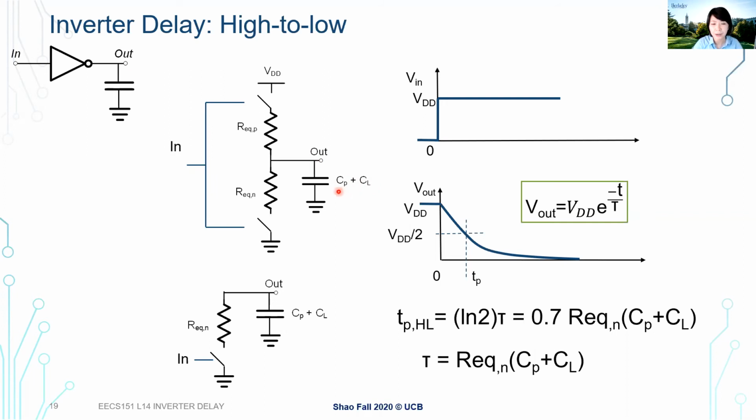At the same time, whenever we think about transistors, there's also parasitic capacitance associated with the transistor itself. So the capacitance affecting the output is a combination of the load capacitance, things happening after my output, and the parasitic capacitance, things happening in my gate. No need to worry about that; we'll just combine them together. Both factors affect the output capacitance here.